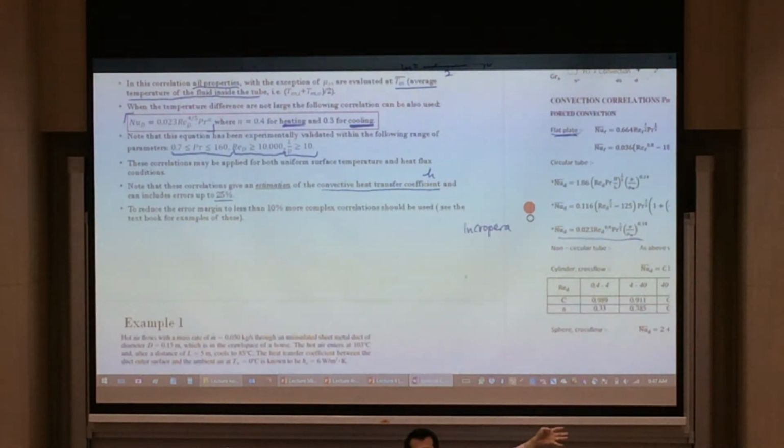This pressure drop is because someone else over at the toilet did a flush, and suddenly you have a pressure drop. So this kind of thing could happen. It affects your readings. So we try to accommodate that. We know that for that kind of dynamic fluid flow, we have about plus minus 25% error. And that's a large error to accommodate.